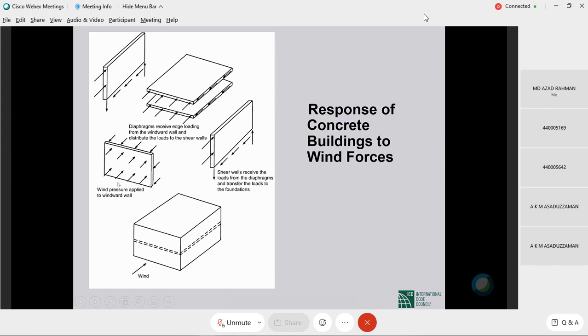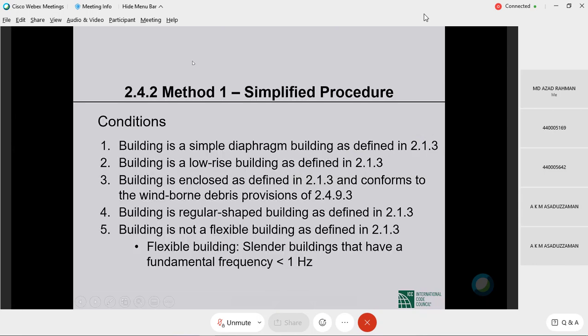So this is a concrete building. Wind is applied on the windward wall, whatever it is made of. This wall bending between supports provided by the slab at the top and the slab at the bottom will transfer the wind to the slabs acting as diaphragms. When we use the term slab, we are thinking of out-of-plane bending under gravity. When the same slab bends in its own plane under lateral loads, we call it a diaphragm. Okay, so this wall will transfer the wind applied to it to the diaphragms, as you see in the picture. Those diaphragms will develop tension along this edge. I'm sorry.